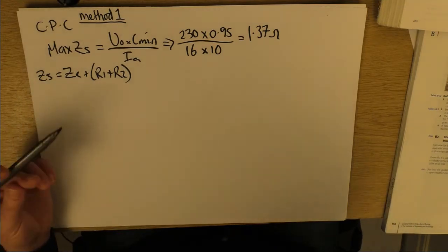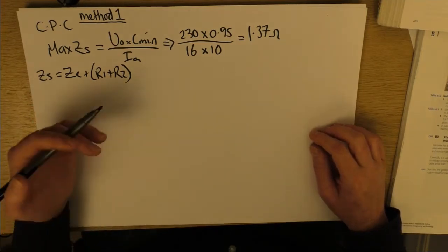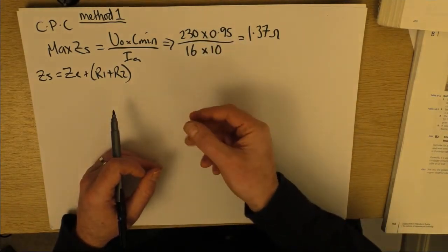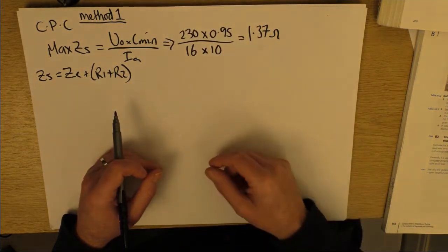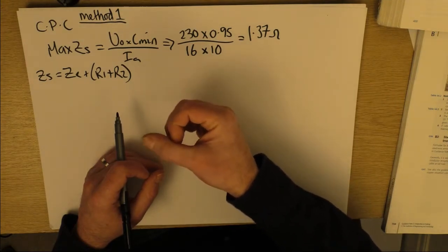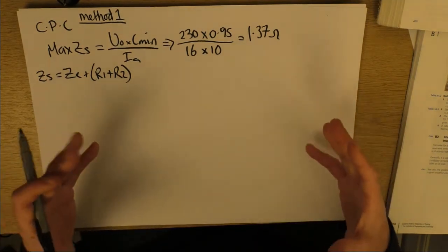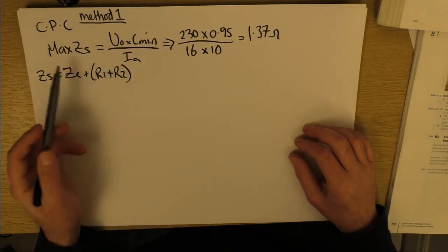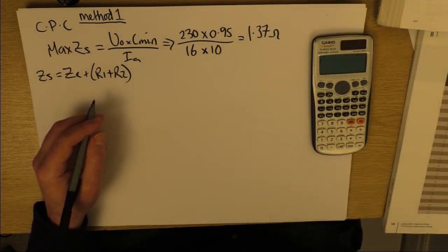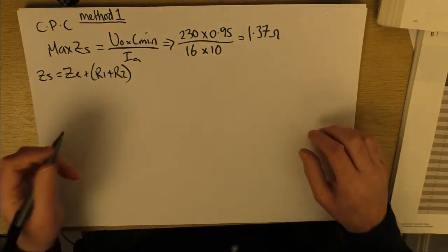I mean, you could calculate it, and calculate inductive reactance. It's 2 pi FL, but it's the L that's the problem in calculating. And especially with singles, it's not uniform, is it? It's not bunched in exactly the same way all the way through. In a cable like a 3-core or a 5-core, they're together and predictable, so it's easier to calculate that. So for submains and big stuff, it might be worth doing, but for these kind of things, we're just going to use the resistance tables either in Guidance Note 3, page 148, or the On-Site Guide, I think it's page 196 or 198, it's table I1 anyway.